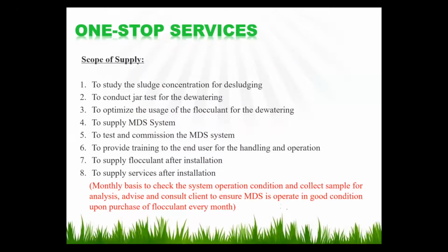I-Chem also provides one-stop services to our customers. So the scope of supplies: the first one is to study the sludge concentration of this sludge. So we will collect your sample to study the concentration before sizing the appropriate MDS for your factory, and conduct a jar test for dewatering, optimize the usage of the flocculant for dewatering, and supply the MDS system. During the supply, we will test and commission the MDS system, provide training to the end user for handling and operation, and also supply the flocculant after installation, and provide service after installation.